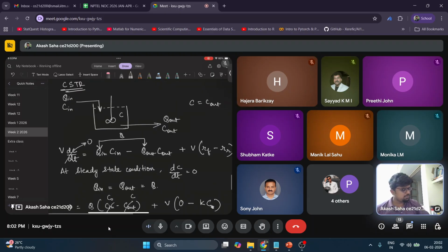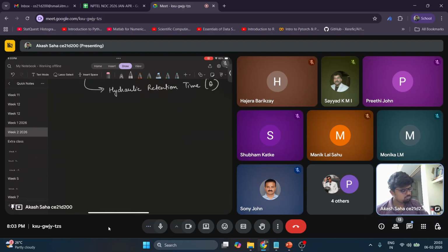Okay, so simple thing. So C is equal to C naught e to the power minus kt. So 3.5 is equal to 21 into e to the power minus k into what is the t? That is 30 minutes. So if I am keeping it as 30 minutes, the answer I will be getting will be in per minute. So the k I will get as 0.0597 per minute, because the unit of k is per time, so per minute. And if I change into seconds, it will be in per second.